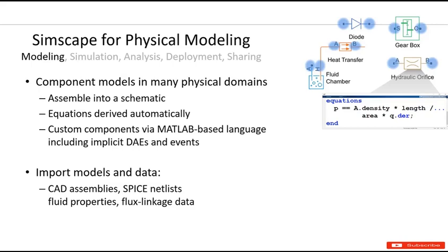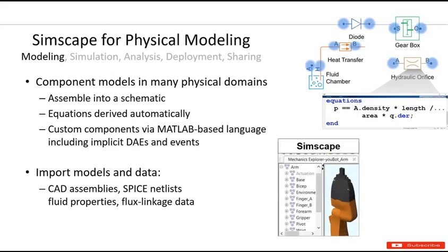But in Simulink, that's the difference. In Simulink, you model your system based on mathematical equations. So if you have a system described by a differential equation, in Simulink you would use those equations in modeling, but in Simscape all those blocks are physical blocks, which you can directly use. So it's a lot easier than Simulink.